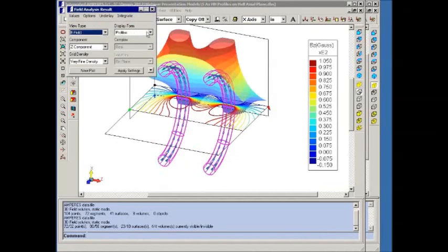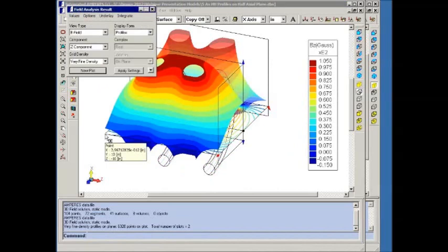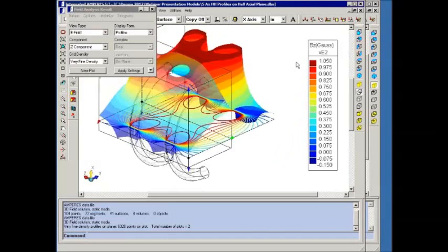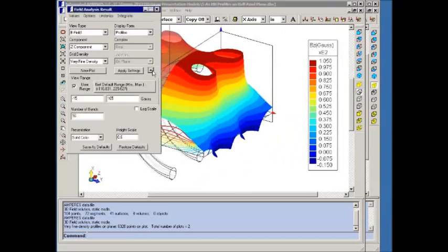So now I want to do a B-field profile plot, very fine density, the Z component, and you can only plot profiles, the grid location is restricted to the plane. So now I'll click on the New Plot button, and then I'll pick these points. Alright. And you notice that my previous plot I'd made semi-transparent, whereas this new plot has no transparency setting, but we can change that.